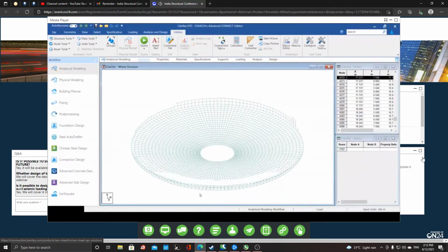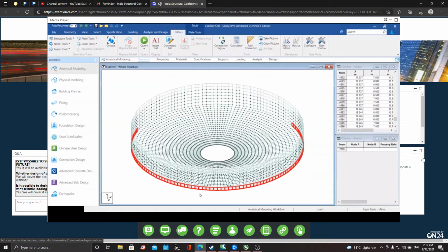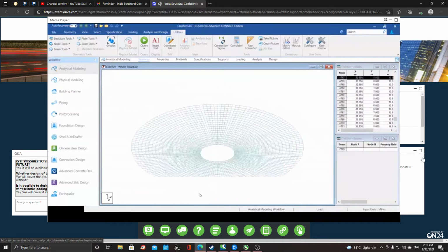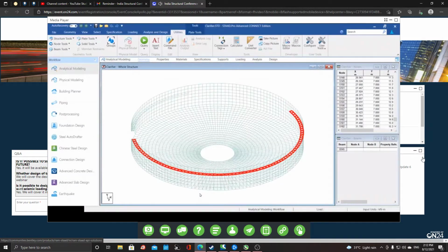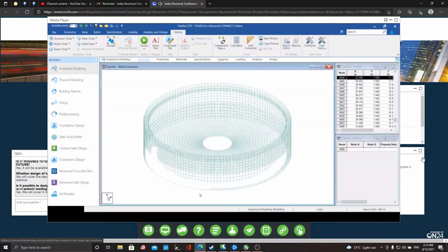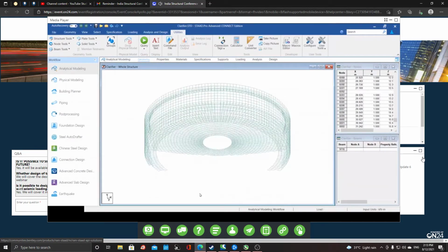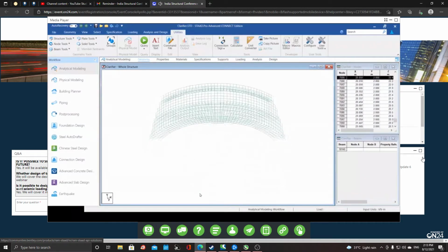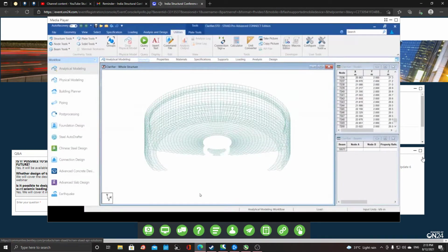And here in this case, we have selected the equal divisions, but as I told you, you have the flexibility of choosing these divisions on your own, so you have both the options available. And then the launder slab and the wall have been modeled. Then again, the footing wall provides a similar option as the tank wall. And then the heel of the tank wall has been modeled, and then the toe. Please note that each and every part of this clarifier will be added in a separate group, so you should be able to select that.